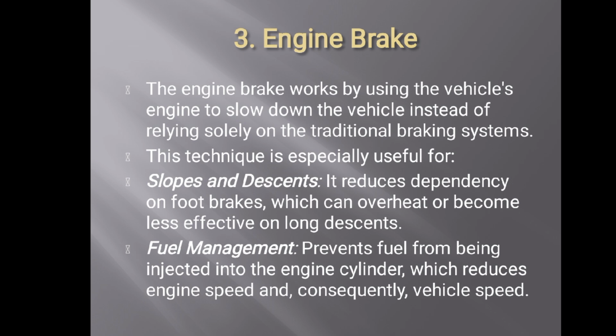The third type of brake is the engine brake. This type of brake depends on the vehicle's engine to slow down the car. The benefit of this brake system is it reduces reliance on the foot brake, preventing wear. And the other benefit is it helps maintain speed control on downhill slopes by limiting fuel injection. So these are the benefits of the engine brake.